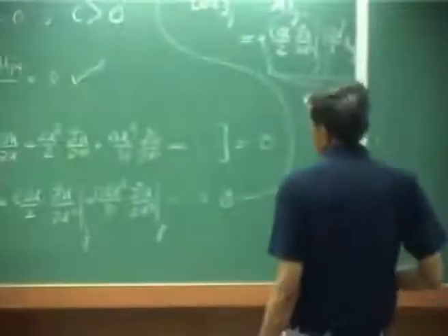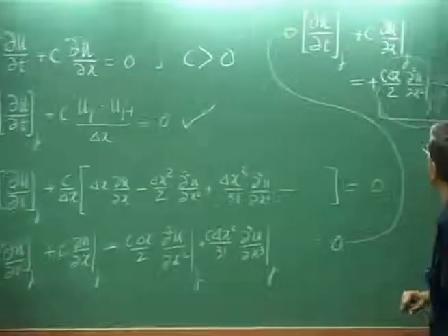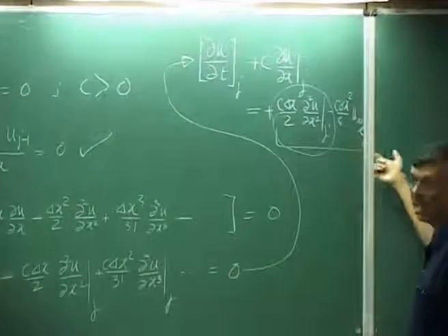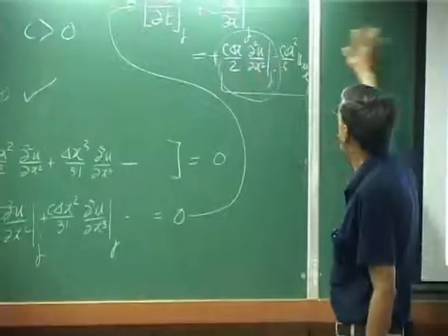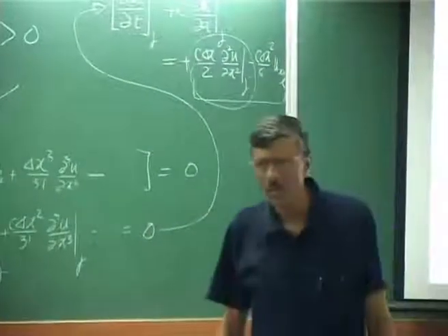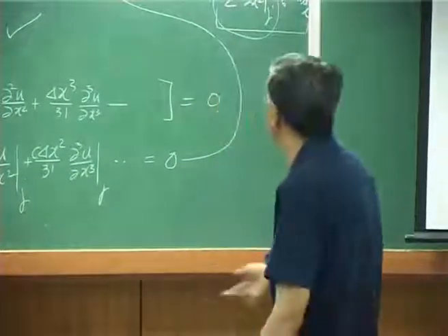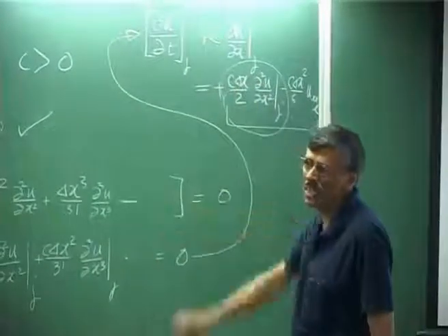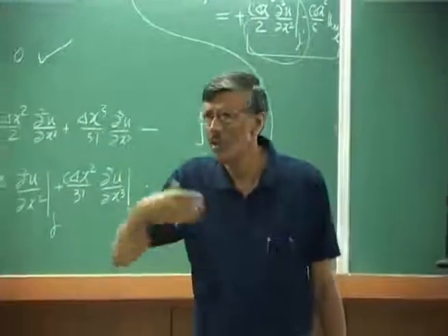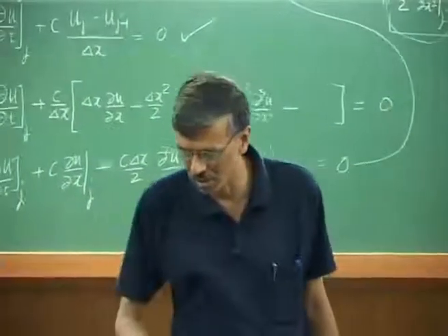However, taking that particular stencil for the first derivative amounts to having this kind of terms on the right side. And you do understand that there are a whole lot of terms there. The one which will dominate the dynamics would be the leading term, because everything is proportional to the grid spacing. If the grid spacing itself is small, the higher derivatives would trail off in terms of their importance.